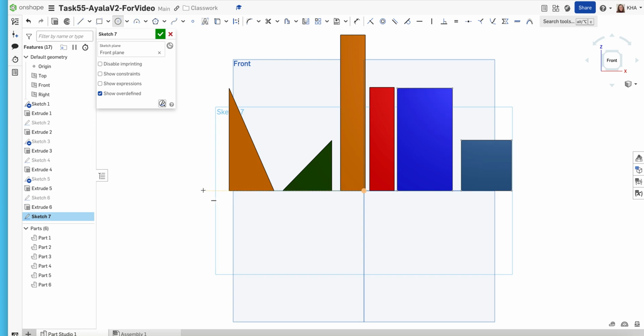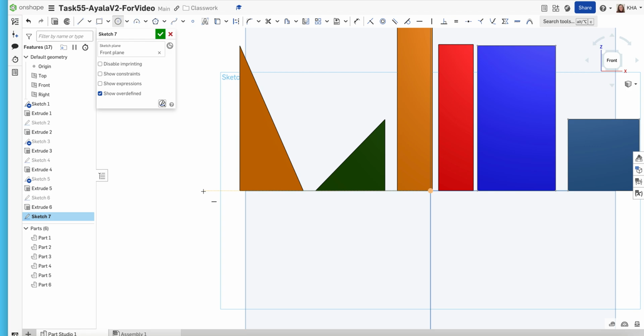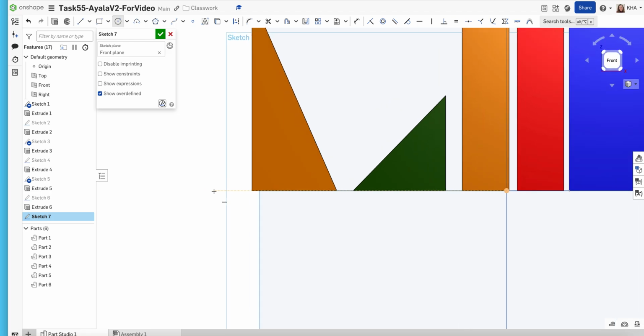Notice, I'm going to try to zoom in a bit here. If I put my mouse in an area that is going to intersect with the x-axis, I get this dotted orange line, and I also get the horizontal constraint symbol. Note that's that little line near my cursor. You see that little line appearing? So we actually do want that to happen. We want to be on the x-axis, so let's go ahead and put a point down on the x-axis somewhere.